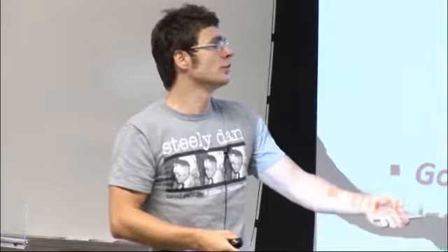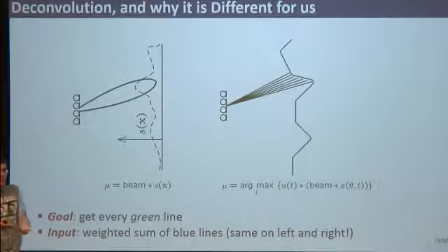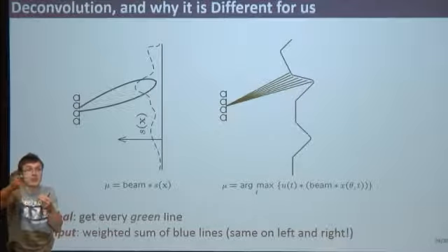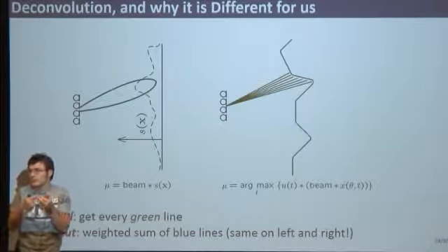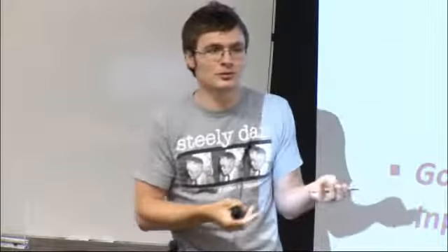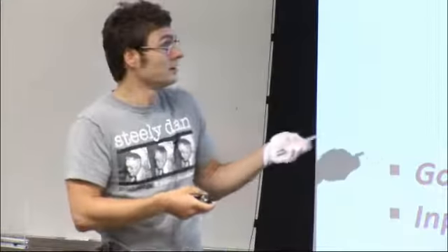Then what we do is we cross-correlate this with our pulse template in order to find peaks, right? So I just wrote it as a convolution with some pulse template u, and then we actually create the pixel by finding the largest peak. So this is the time of the largest peak, and this is our depth, right? Obviously this is not a linear model because there's a maximization inside. We cannot write this out as a matrix multiplication of some true depth image with some beam shape. Our measurements are not linear, and so there's no hope to just do very simple deconvolution, as is the case in the linear intensity images. Hope this is partially clear.